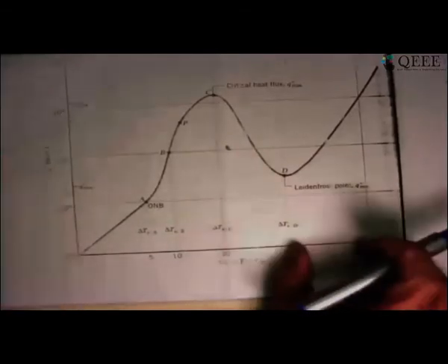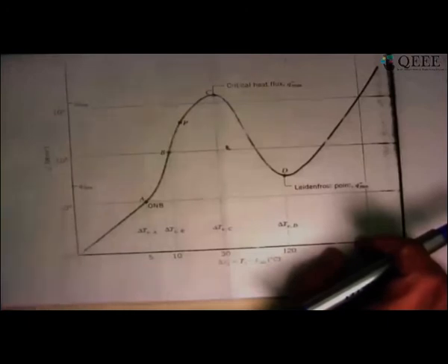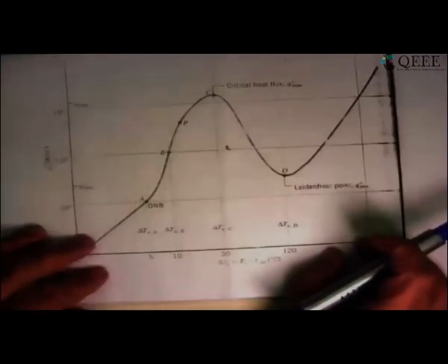In the next situation, something else is now happening. From this point onwards, when the surface becomes hotter and hotter, and this is the type of thing we would say, power plant boiler tube or something like that, 500 degrees Celsius is the surface temperature. Then again, heat transfer rate begins to increase, and now here 2-3 different things start to come into play.